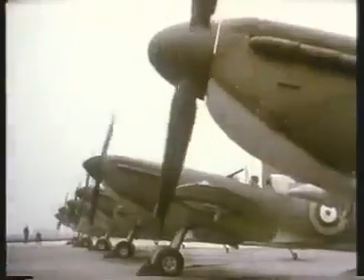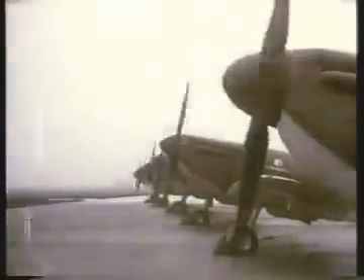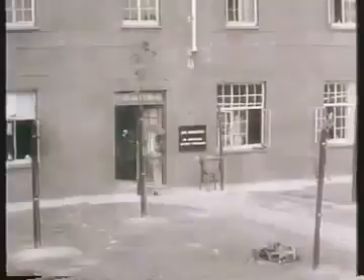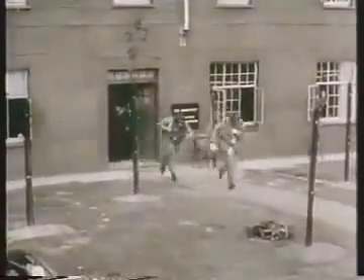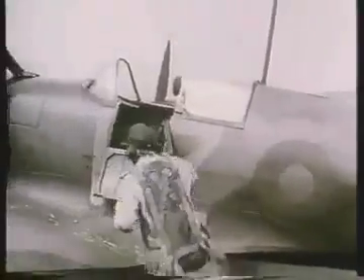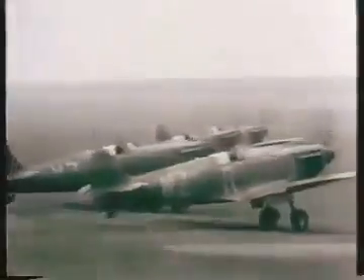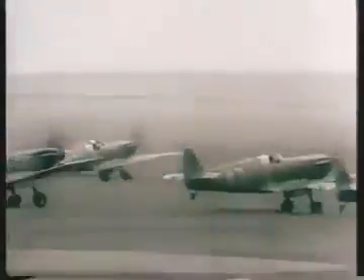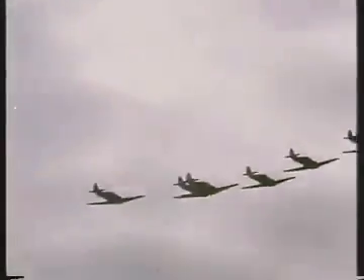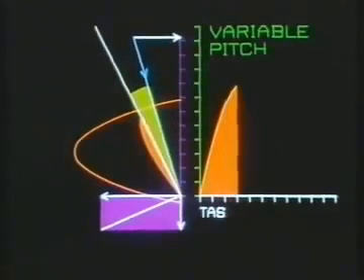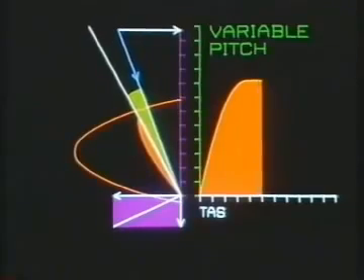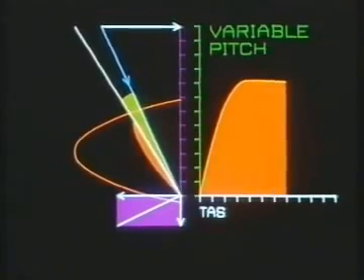This problem was eliminated in Spitfires and Hurricanes by converting their two-pitch propellers to variable pitch units shortly prior to the Battle of Britain. This also shortened takeoff runs, increased rates of climb, significantly improved maneuverability, and lifted their operational ceilings. The introduction of variable pitch enabled the propeller to work close to its maximum efficiency over a wider speed range.